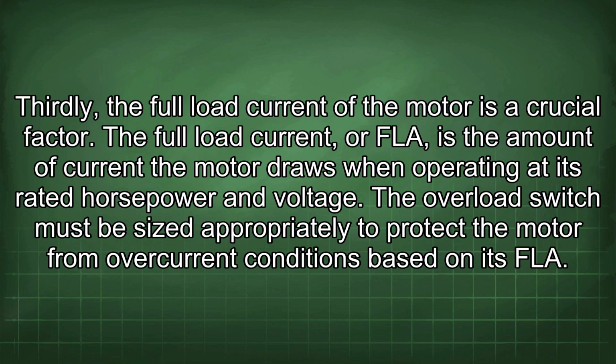Thirdly, the full load current of the motor is a crucial factor. The full load current, or FLA, is the amount of current the motor draws when operating at its rated horsepower and voltage. The overload switch must be sized appropriately to protect the motor from overcurrent conditions based on its FLA.